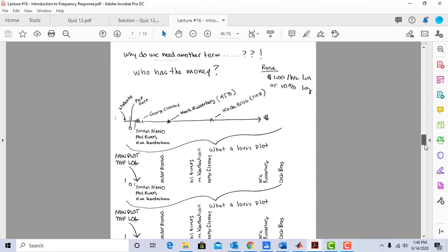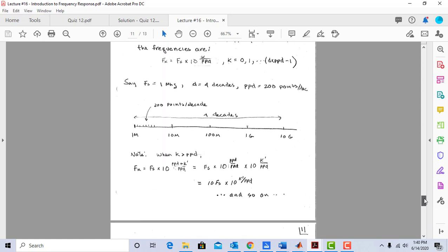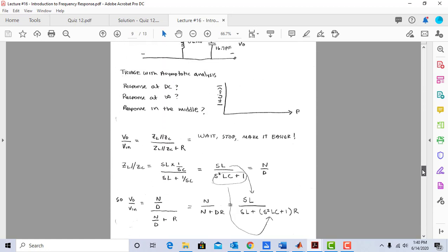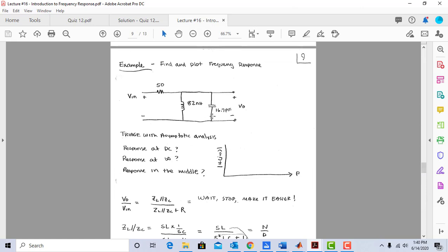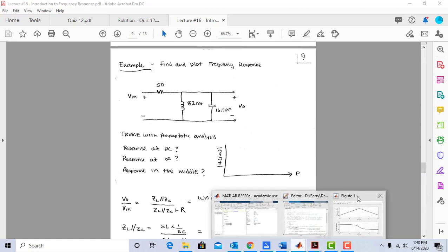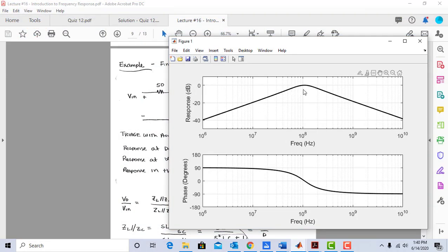Let's go back to our filter first. Here's our little bandpass filter. Here's the frequency response. Did we make the filter that we needed for that airplane to receive the VOR station but reject KGB FM? Well, no. The reason we didn't is our filter doesn't have enough what we call selectivity. In other words, we made a filter that peaked at 108 megahertz. That's great, but the trouble is at 101 megahertz, it's pretty much going to let that pass through.